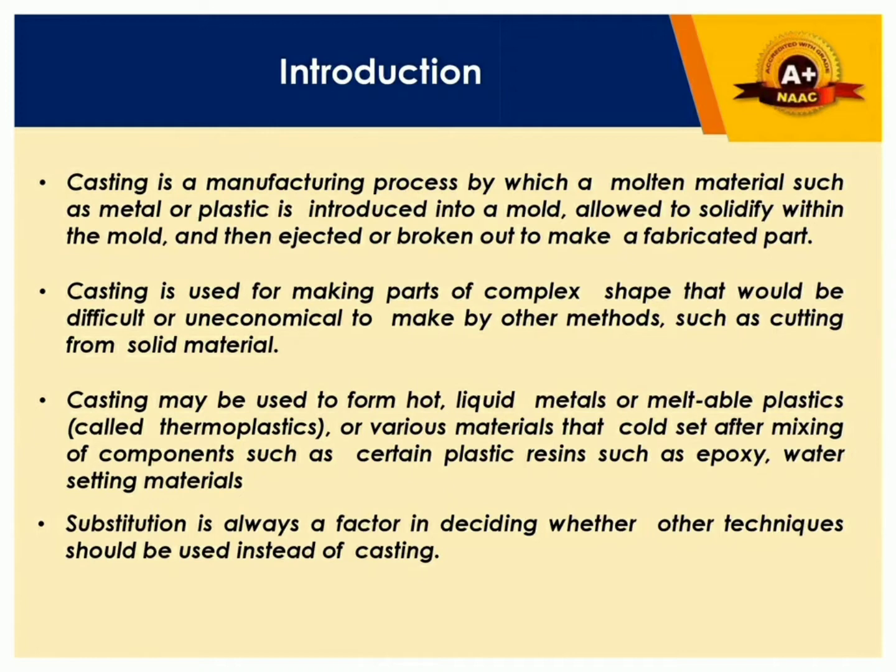Casting may be used for hot liquid metals or meltable plastics called thermoplastics, or various materials that cold set after mixing, or components such as certain plastic resins such as epoxy, water, or other setting materials. So casting is not limited to metals; it is also applicable to different types of polymer materials, like plastics or thermoplastic materials. Substitution is always a factor in deciding whether another technique is used instead of casting.